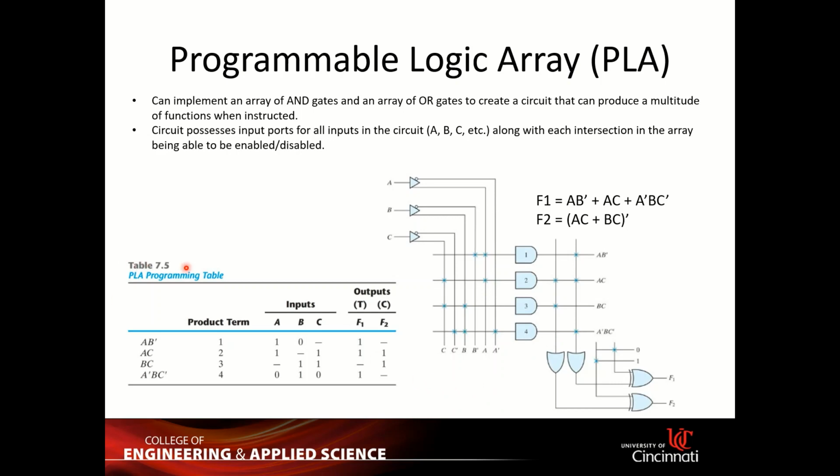Another thing that you should know is the fuse map of the PLA. If you can describe that in terms of an array like this with burning fuses, you can also specify that in a tabulated or a table format. So for example, the programming table consists of 3 sections, right? Product terms, input, output.